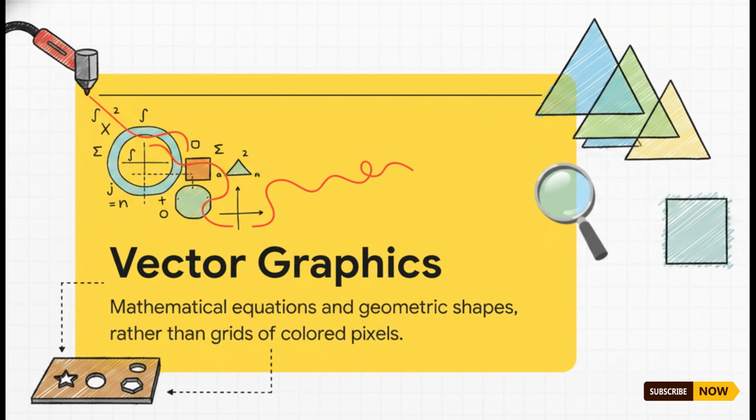If you're used to working with JPEGs or PNGs, well, those are raster graphics. They're just static grids of colored pixels, and a laser cutter doesn't have a clue what to do with a pixel. Instead, it needs vector graphics. These are built entirely on mathematical equations that define exact lines, curves, and polygons. This is absolutely essential because vector paths can scale infinitely without losing a drop of quality. They give the physical laser head an exact continuous coordinate path to follow, which ensures absolute geometric accuracy.